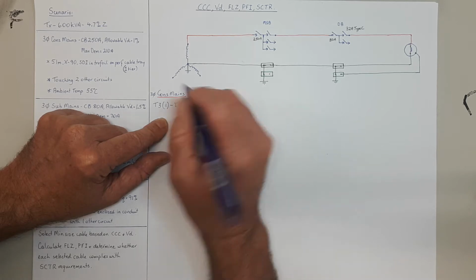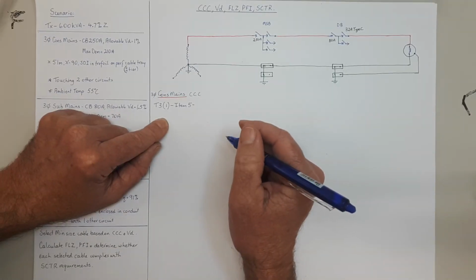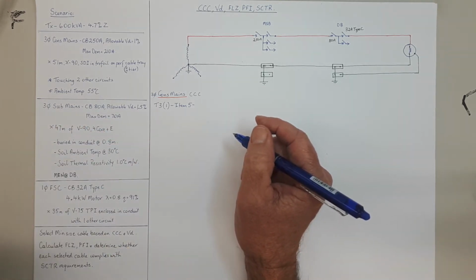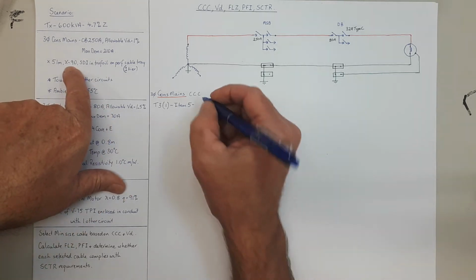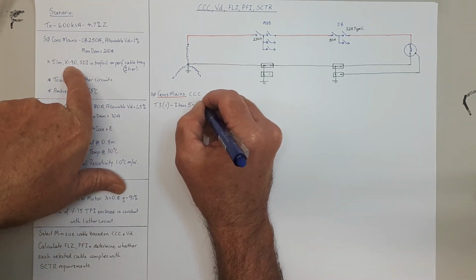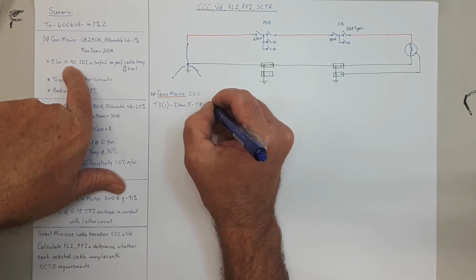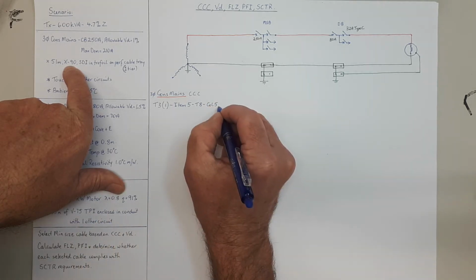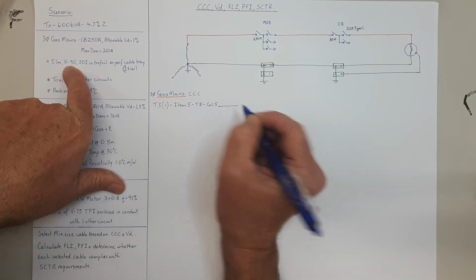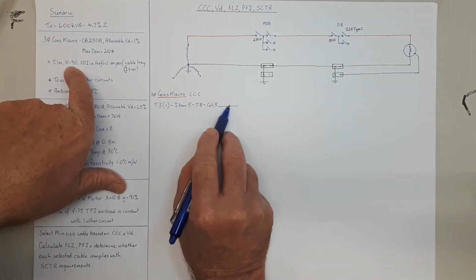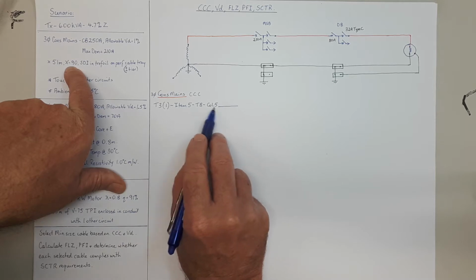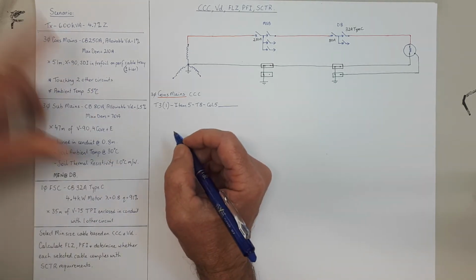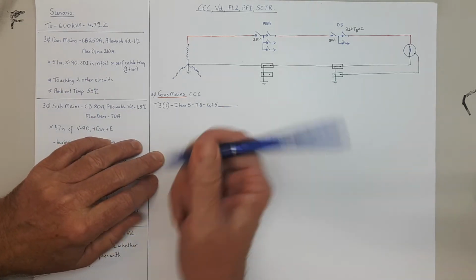So we're going to item 5. If you run your finger across, you find table 7 and table 8, and we know that it's table 8 because it's X90, and we know that it's column 5 because we assume it's stranded. Always assume the cable's stranded copper unless you're told otherwise. And so that's where we come back to. This is table 8, column 5. That's where we're going to come back to at the end to work out what size cable we need. So first thing you need to know is that there's a derating.